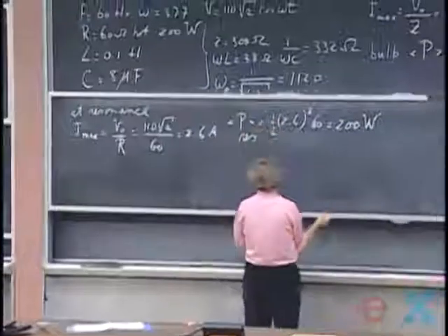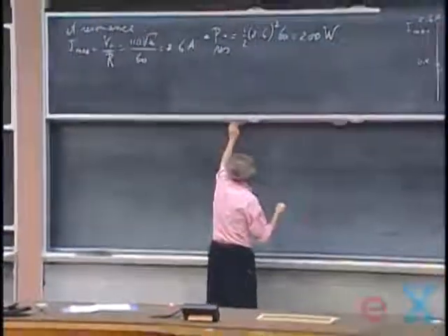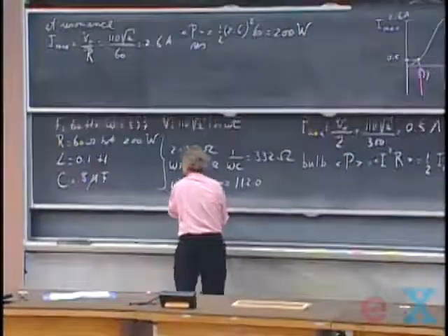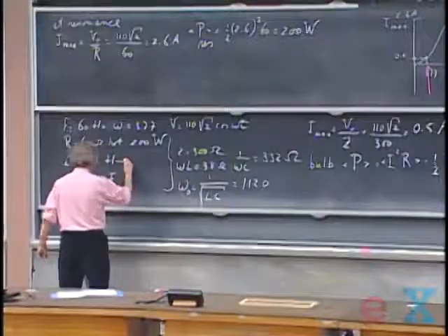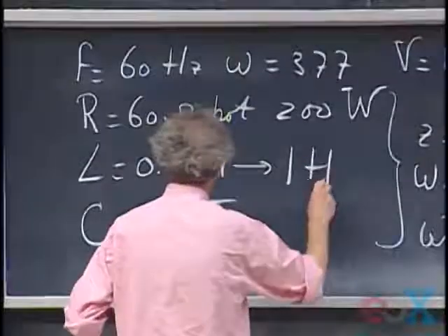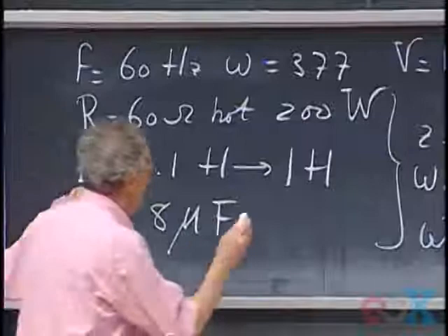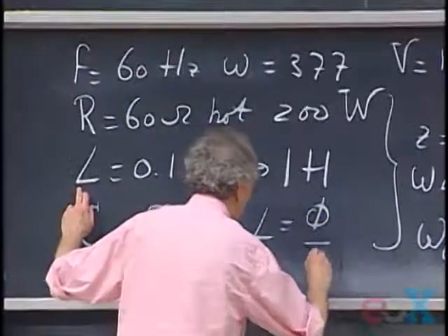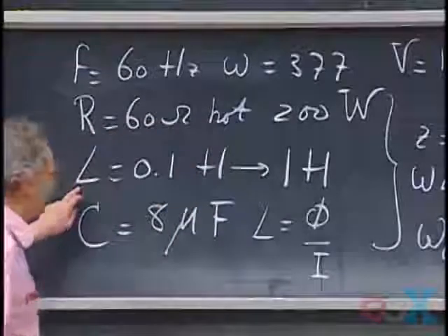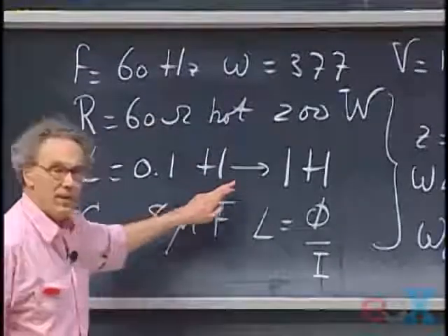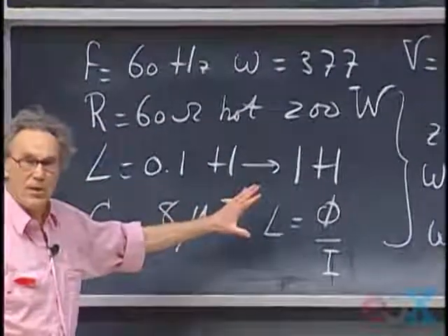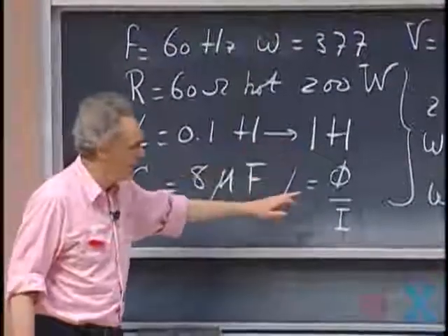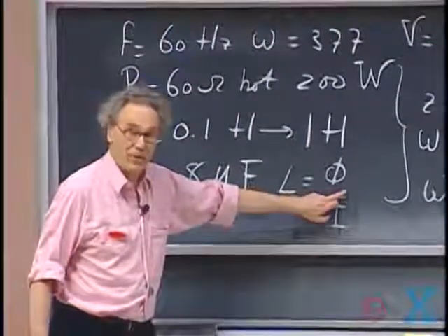So that means that if I bring that iron core inside, that I could make this go up to 1 Henry. Because remember, the meaning of self-inductance is the flux divided by the current in the solenoid. And so if you bring in ferromagnetic material with a kappa M of 10, then the flux goes up by a factor of 10.